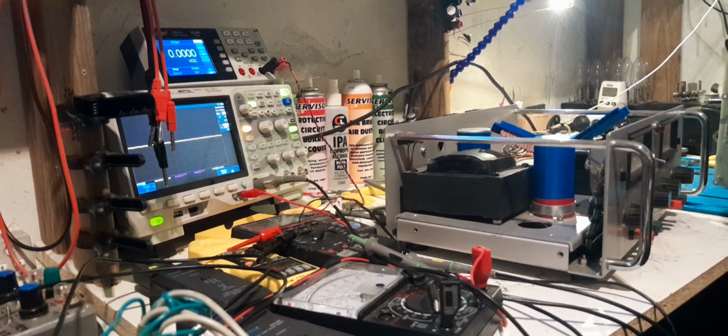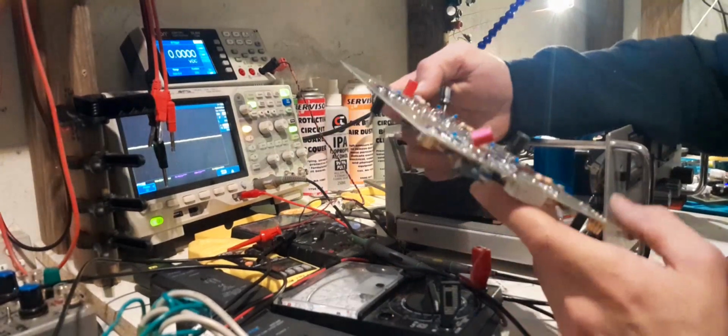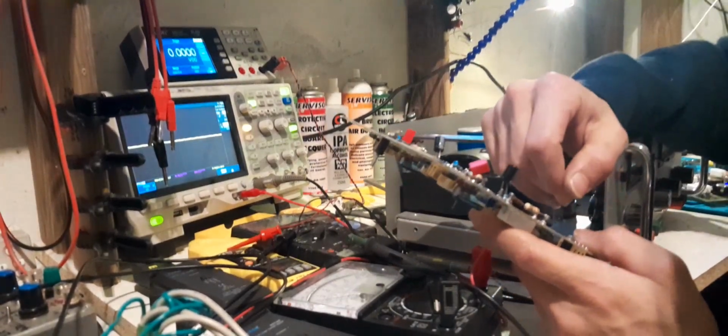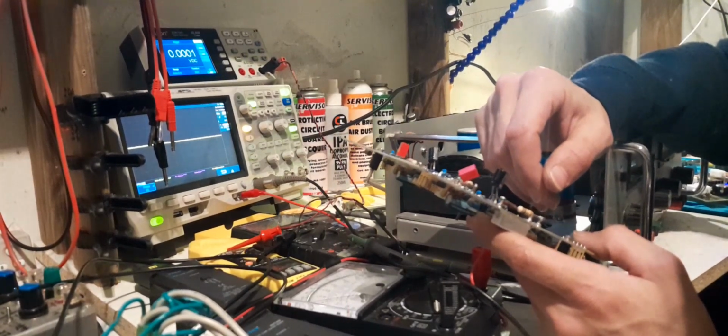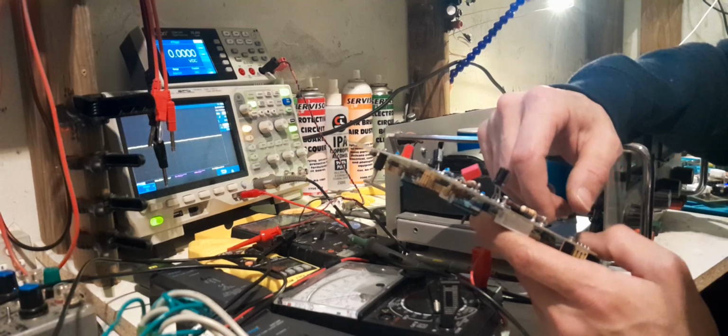Anyways, what I was about to show you guys on the scope before I just fried my board was that last night the only way I could get the reference to be a little bit quieter, with or without compensation on the op amp, was to literally put 47 microfarads across it.